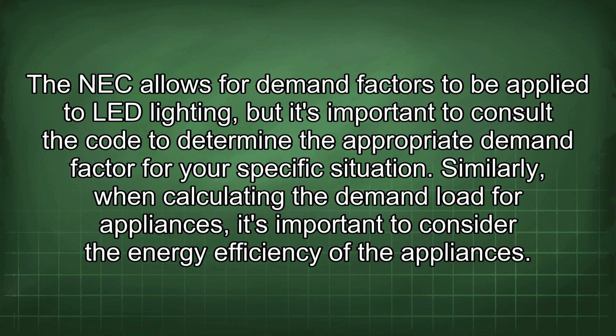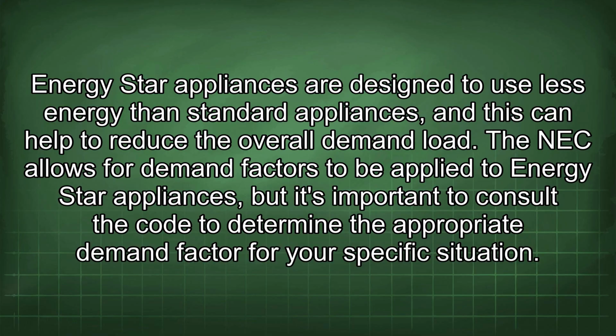Similarly, when calculating the demand load for appliances, it's important to consider the energy efficiency of the appliances. Energy Star appliances are designed to use less energy than standard appliances, and this can help to reduce the overall demand load. The NEC allows for demand factors to be applied to Energy Star appliances, but it's important to consult the code to determine the appropriate demand factor for a specific situation.